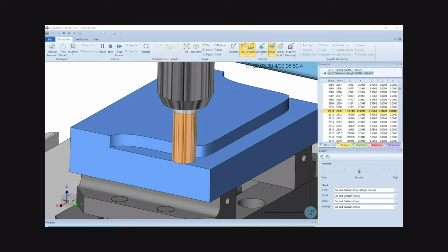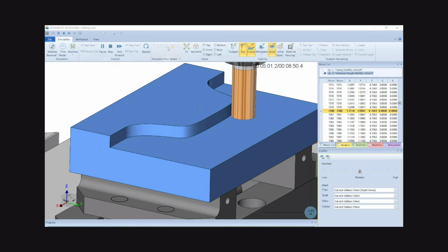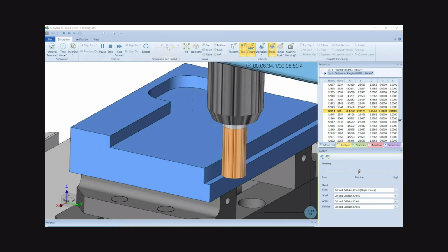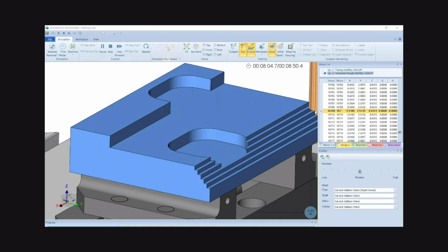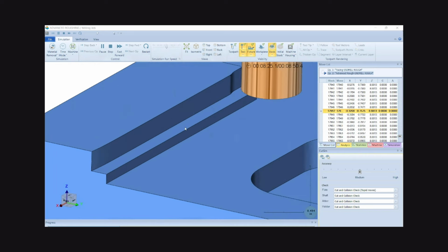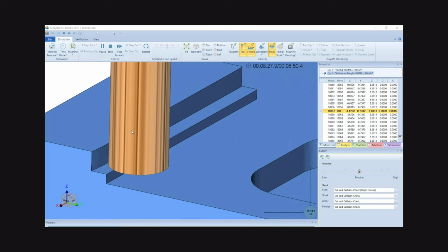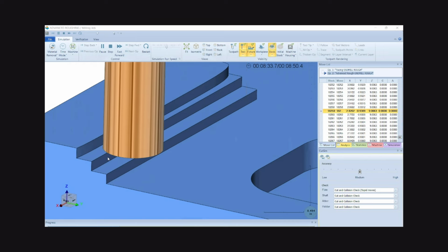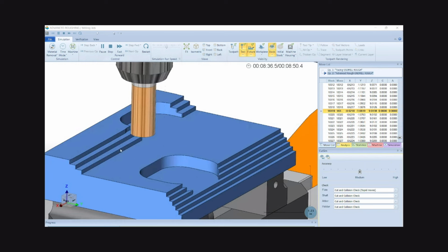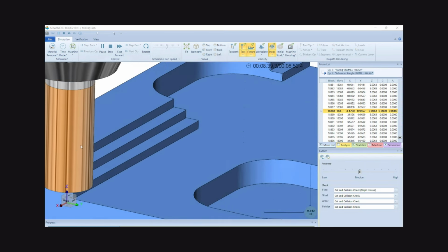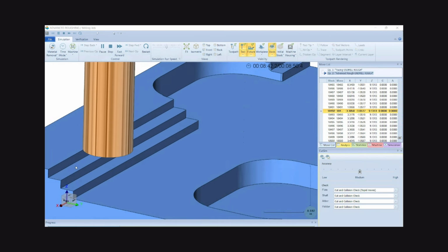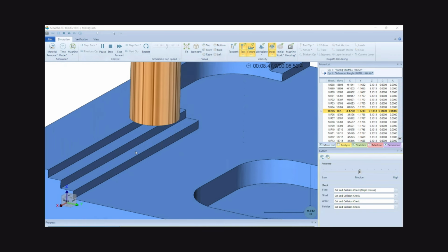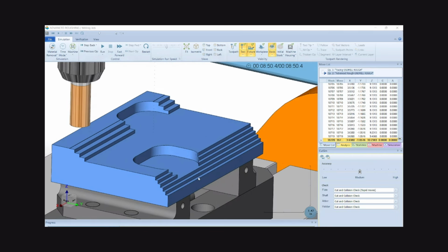And once it gets down to the bottom, after my 1/2 inch depth of cut at each step there, you can see that it comes back up with a couple of steps up there. You can see 3 additional steps. That is our intermediate steps option. So once it goes down to the full depth, instead of having all of this additional material to be finished, it's going to add what they call stair stepping as well. It'll add additional steps in the toolpath to clear out a bunch more material for your finish operation.